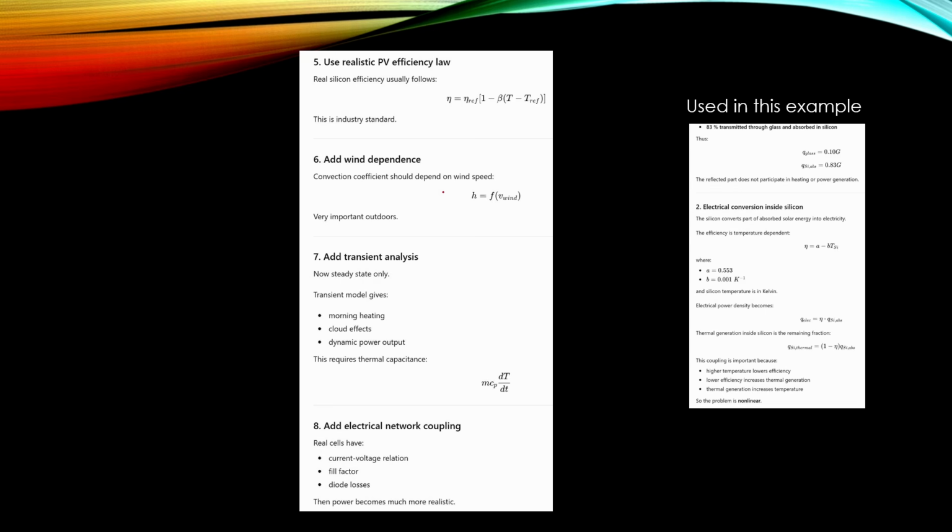And if you know the wind speed, you can calculate this heat transfer coefficient. We have now been using fixed value 35 watts per square meter Kelvins. If the wind speed is very low, then you need to move to using natural convection function, and then this heat transfer coefficient is typically below 10 watts per square meter Kelvins.